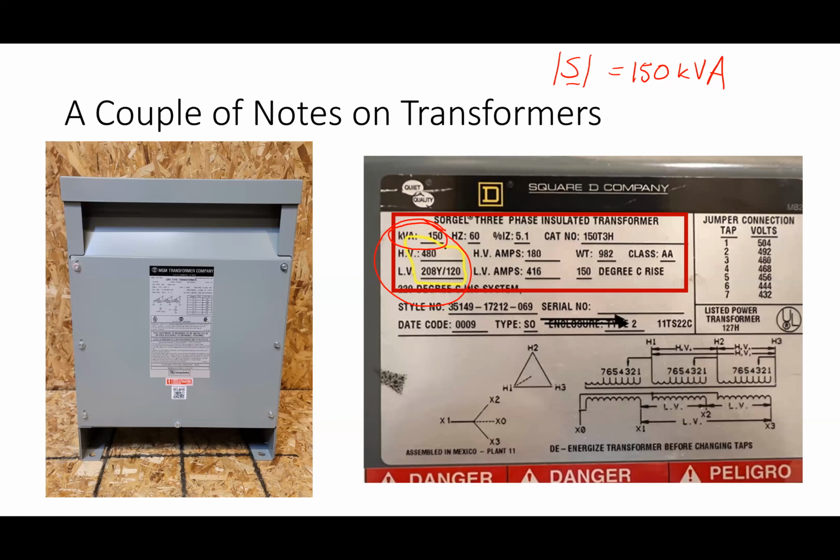Basically, the maximum amount of current I can pass through here. If I pass more current than whatever this rating tells me, transformers can get too hot. It's a thermal rating that controls the rating of the device. So I think in the homework on number 5, I told you it was a 50 kVA transformer. From that, I think you get the current number.